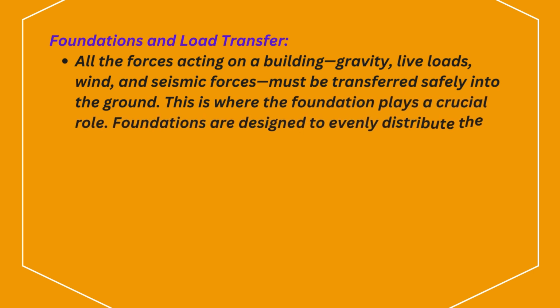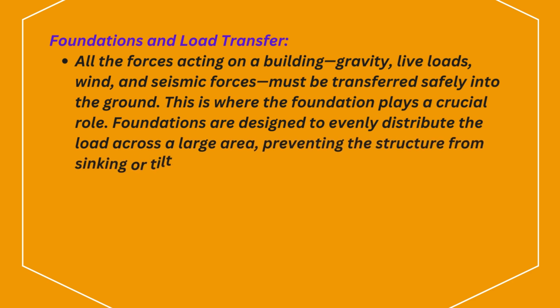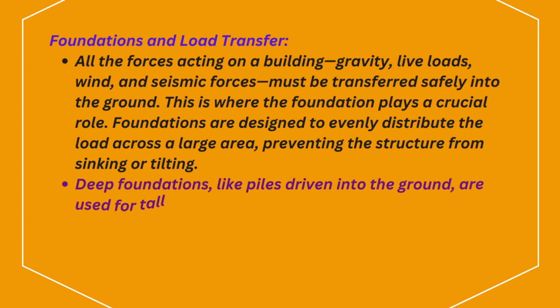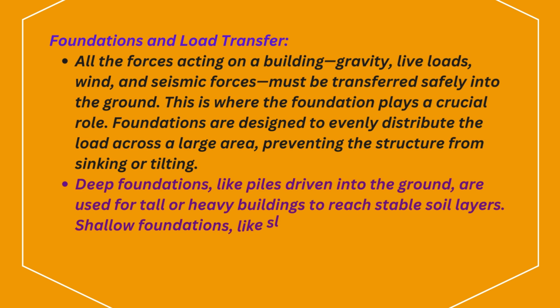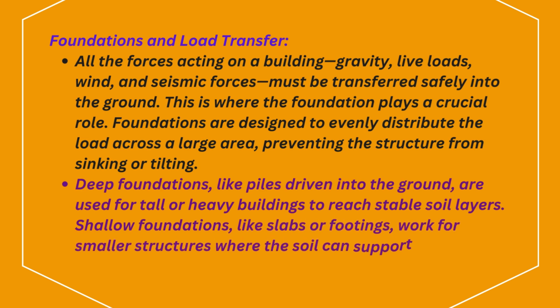Foundations are designed to evenly distribute the load across a large area, preventing the structure from sinking or tilting. Deep foundations, like piles driven into the ground, are used for tall or heavy buildings to reach stable soil layers. Shallow foundations, like slabs or footings, work for smaller structures where the soil can support the load at surface level.